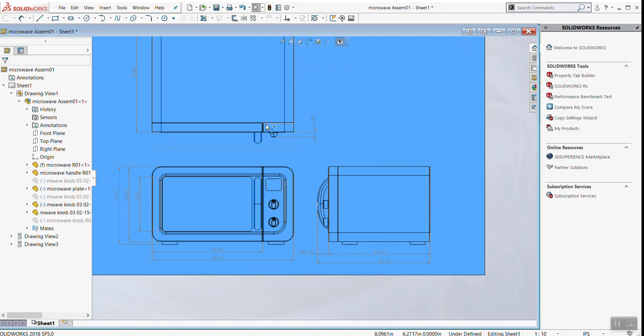So if you start with best practices, know that giving too much information creates a chance for conflicting information. To avoid that, write ref if you have a double dimension. It's best practice. Again, for this project, you don't need to worry about it as long as you give me a front, top, side view with overall width, overall depth, overall height. You get good grades on that portion of the project. Any other questions?